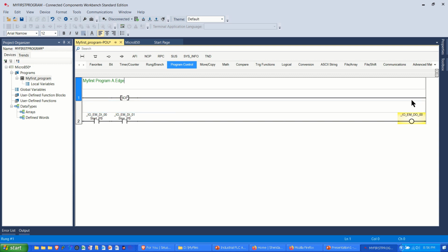It does not impact my scan time. It does not impact my program flow. I can turn around and say, this is my first program. This program allows the clamps to close on the part. This program monitors the photo eyes looking for the part on the conveyor. Whatever the program does, it allows you to take a big project and put it into smaller, digestible, quick, easy to troubleshoot batches of rungs of logic, and then identify it. As I say, it doesn't impact that, but it gives you the opportunity to put in some commentary.